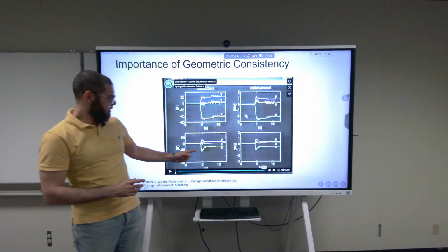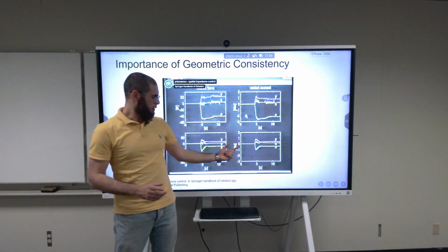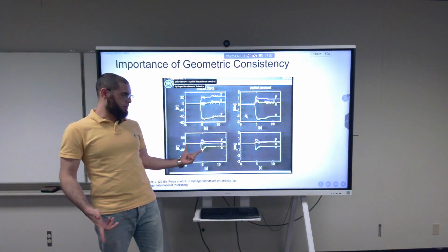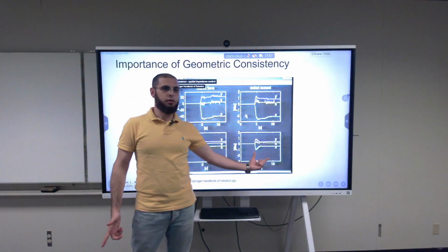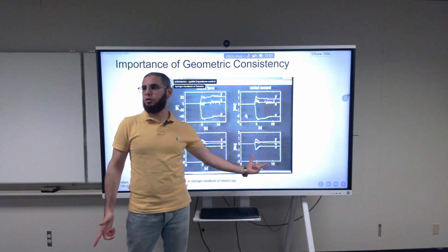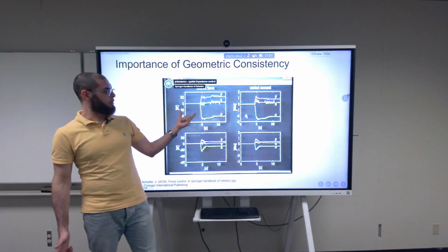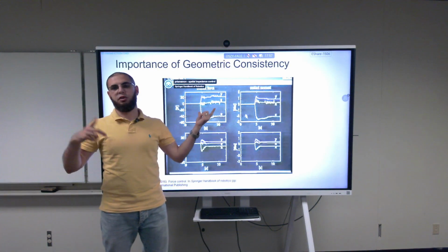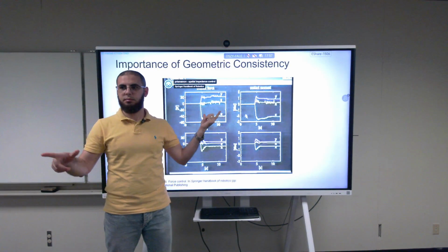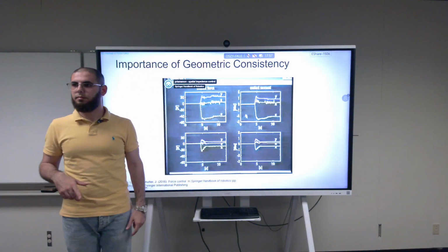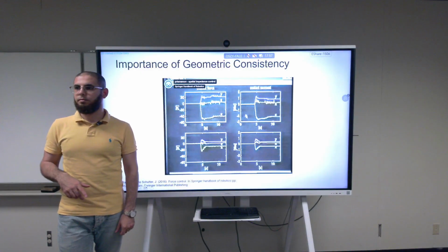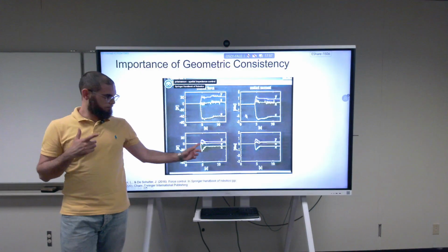So this is the force, okay, that the robot is applying to the environment using the geometrically consistent approach, and the torque the robot is applying to the environment with the geometrically consistent approach, while this is the force and torque the robot is applying to the environment using the Euler angles approach. Something that we also see in the assignment, the Euler angles usually produce much more torque, even though it returned almost at the same speed. Yeah.